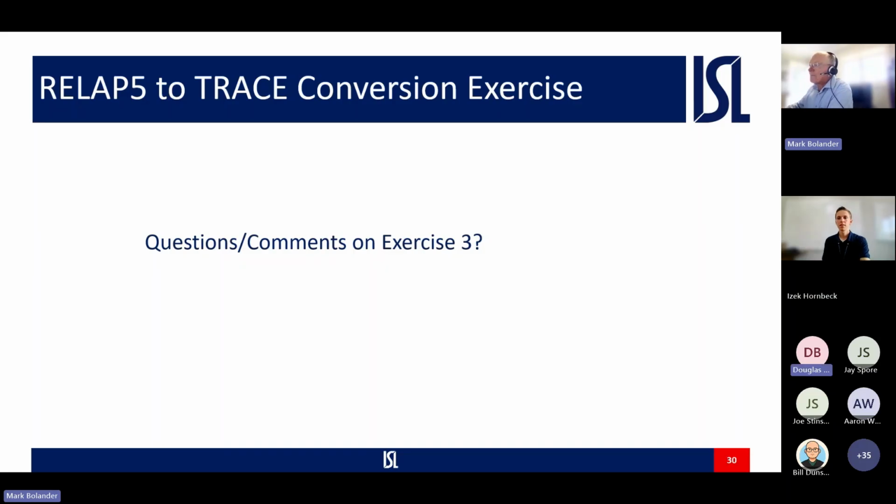We do have one question here from Aaron. Okay. Hey, since quality was mentioned earlier, I was wondering, when you specify a boundary condition in TRACE, it's void fraction and the phase temperatures. RELAP lets you specify other ways such as static quality. Does it attempt to convert those with steam tables, or how does that work? And also, does it always assume water? What if you have a different fluid?